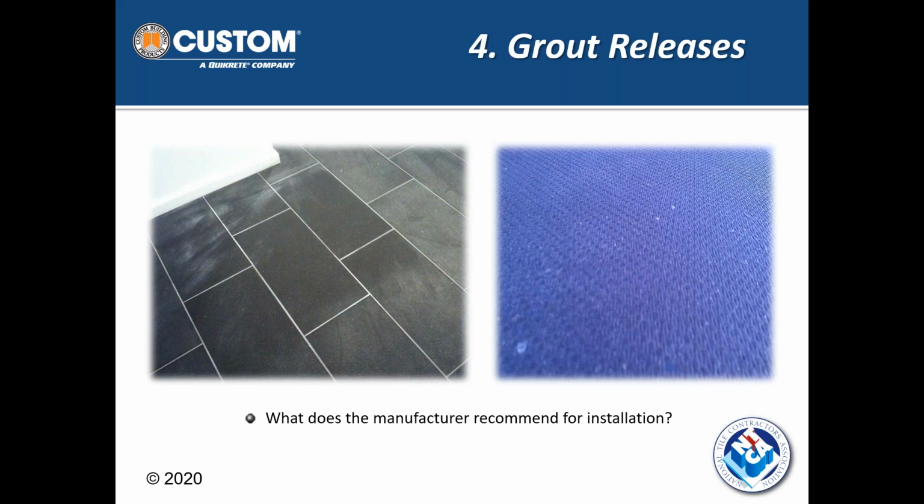And in the process of getting that off of there, there's a lot of washing, which, as most of you know, is not a good thing. So not only did they get the haze off the tile, but the grout color was not supposed to be white or a very light gray. It was supposed to be more complementary. But in that process of trying to wash and scrub, not only did they still not get it all off of there, but we've now lightened the grout color, which is a separate issue. In the middle, where it's darker, that's where they were able to acid wash it and treat it and get it back to the look of the tile to what it should be.